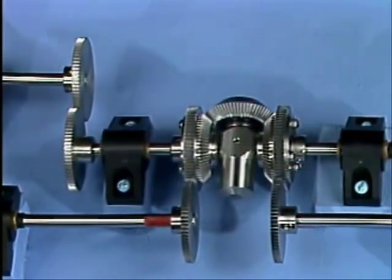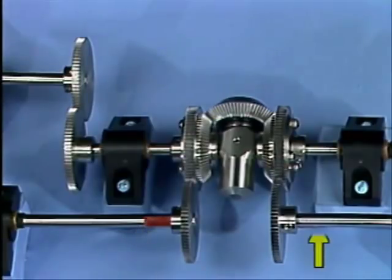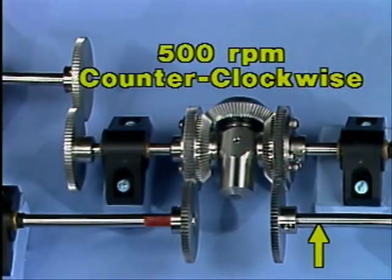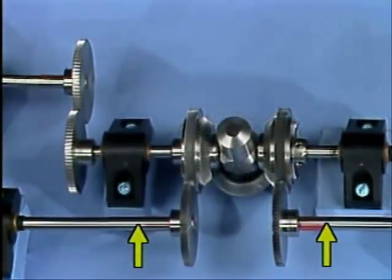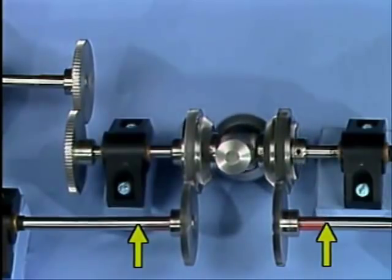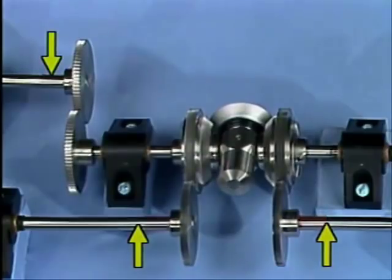To get a better picture of how the differential compares inputs, let's change the speed and direction of rotation of these two shafts. We'll rotate this shaft at 500 RPM in a clockwise direction, and this shaft at 500 RPM in a counterclockwise direction. In other words, we'll provide inputs that are exactly opposite. Since the inputs are exactly opposite, they cancel each other out, and the differential provides no output.